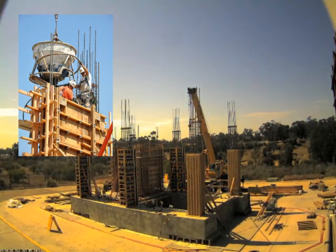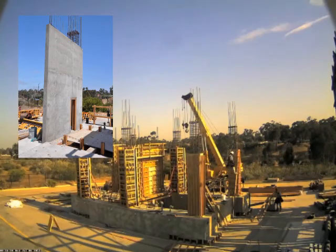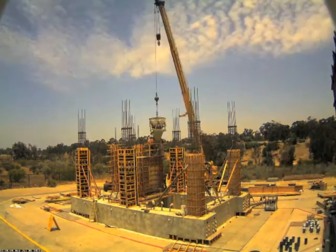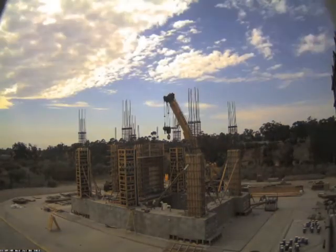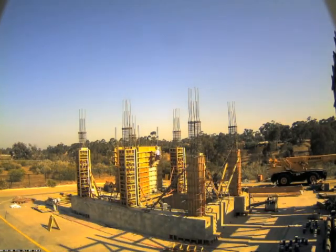Samples were taken from the mix inside cylinder tubes to further evaluate the correspondence of concrete strength to the expected value for construction purposes. After completion of the first floor construction, the fabrication of falsework is required in order to construct the second and subsequent floors. Falsework can consist of beam clamps, braced frames, timber scaffold tubes, and props.